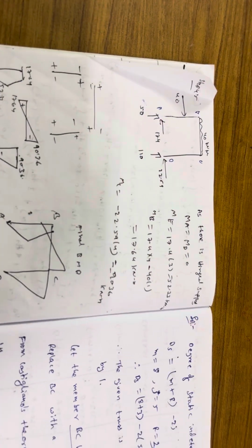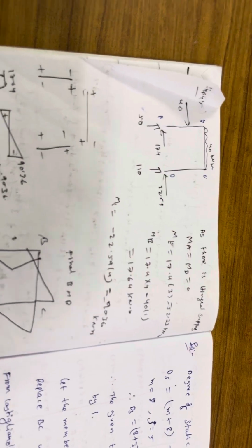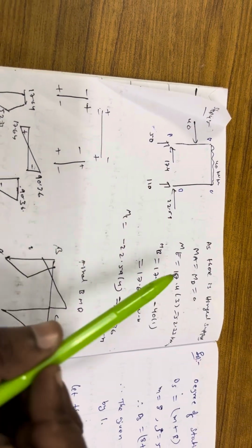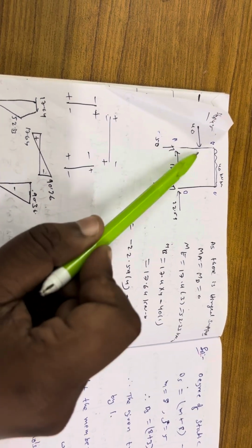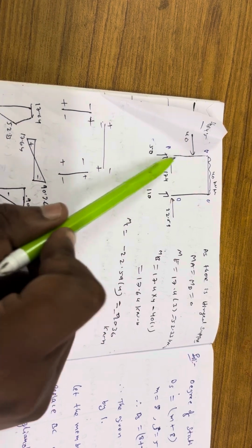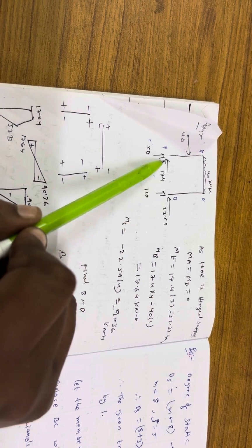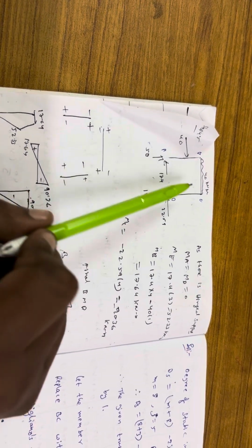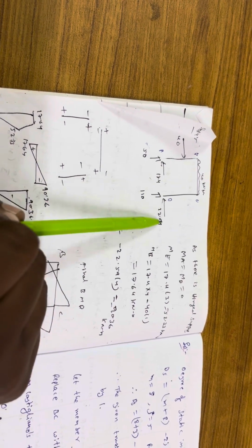Okay. After getting all the equations, as there is a hinged support, now we need to draw the bending moment diagram. Okay. So at A and D, there are hinged supports, so there are no moments. So MA, MD 0. Now what about ME? Moment at E 17.4 into perpendicular distance. Next, what about moment at B? This into perpendicular distance, this into perpendicular distance. Okay. What about moment at C? This into perpendicular distance, but in reverse order, so minus.